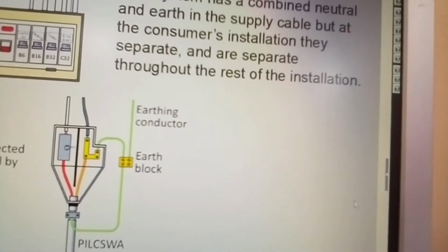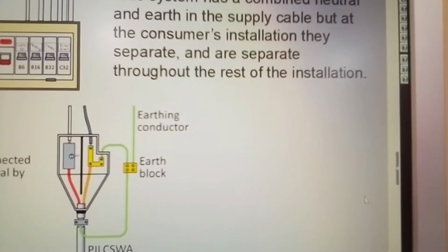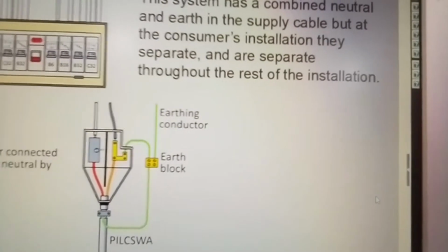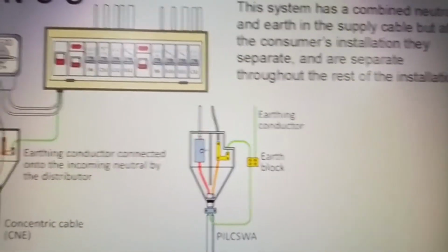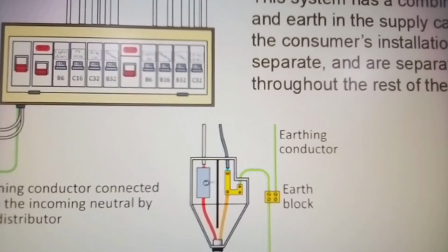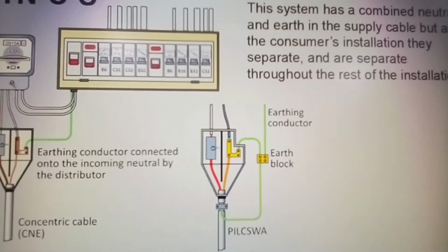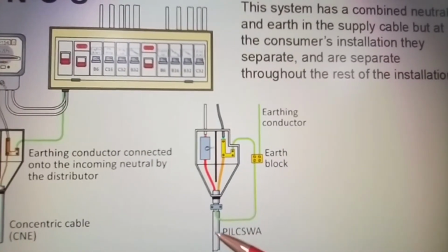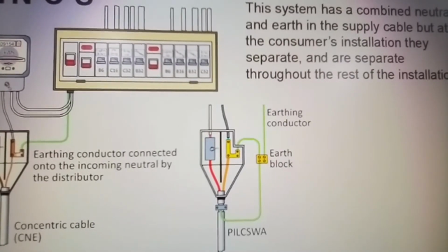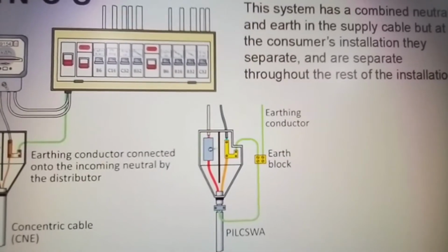Just move across here so you can see this and read this for yourselves, in full. Let me just move in to here so you can see the connections. And this is still wire armoured cable. The size is dependent upon what current you're going to carry, so you'll be looking at 100 amps normally for a household.